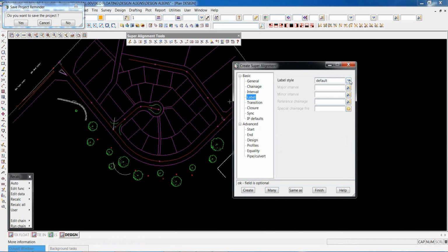So we'll go into the label option and set this up. Even though we're trying to match into an existing footpath, just so we've got a bit of thickness and it looks interesting, we'll drop down here and set this to a culvert, and the width is 2 meters. Don't worry about too many levels, but we could say offset.